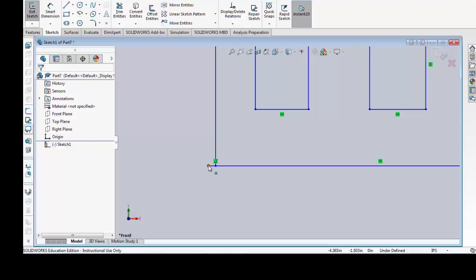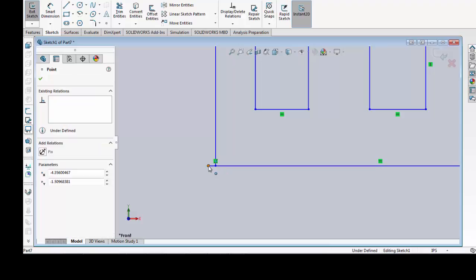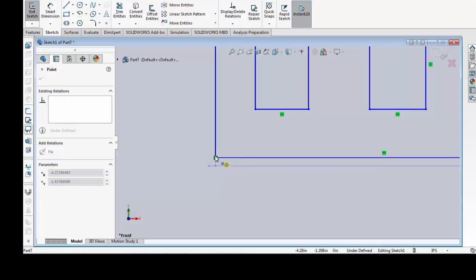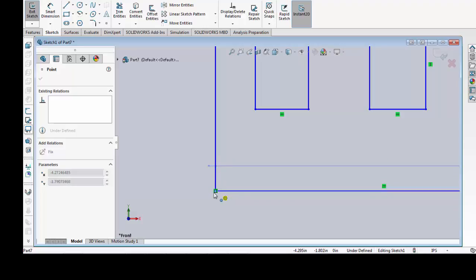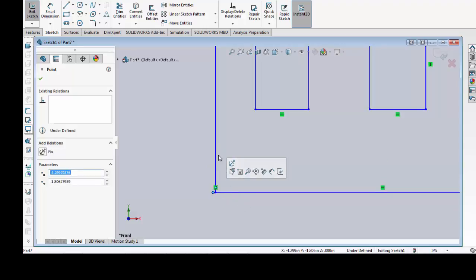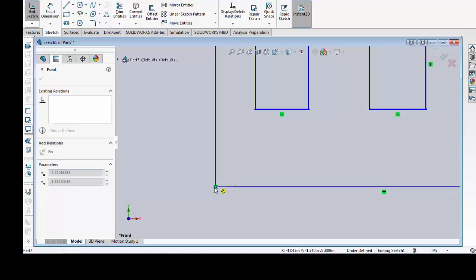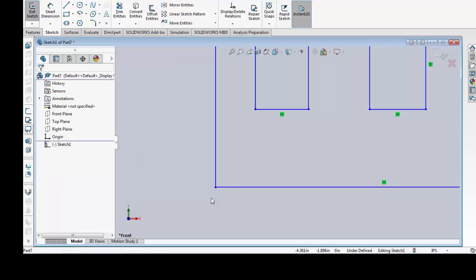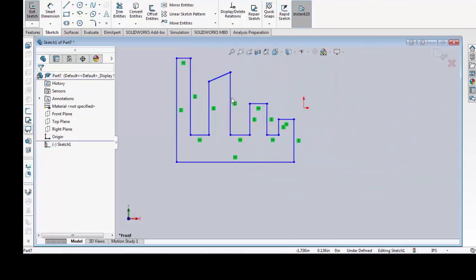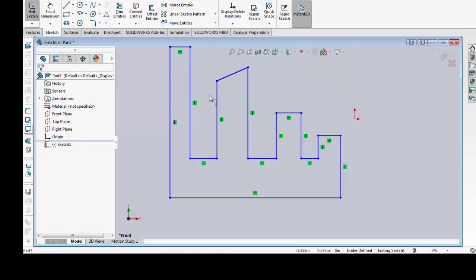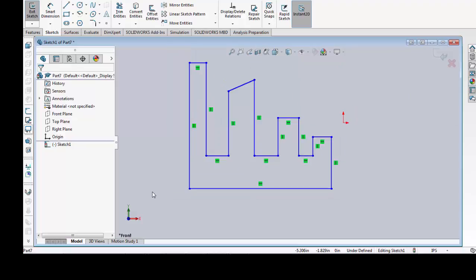This line did not end where it needs to go, so I can click and hold down the button and bring the line back to where it will be aligned to that end point. Okay, if I was to bring it here, it brings both lines down. Notice that the alignment is there, and I can select that to make sure that those 2 end and begin at the same point.